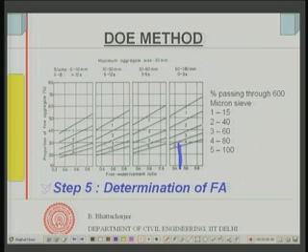I will need much lesser sand now, because my maximum size of aggregate has increased. So, this curve is now coming down, because MSA has increased, the void in the coarse aggregate system is lower. So, I will require lesser fines, right.